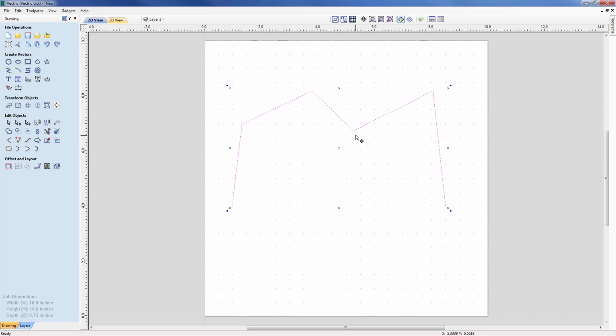So I'm now going to do exactly the same, use the same point here now, but rather than specifying an incremental distance, I can give an absolute position for where I want this to move to. So once again, I've just clicked on the point there and I'm moving this now. I'm not worried about the direction I'm moving in, because I'm going to specify that I want to move this to where this particular point happens to be at 5, 5. So to do that, rather than using the 5, 5, we have to go 5x 5y, and that will have moved that point to the middle of the screen.